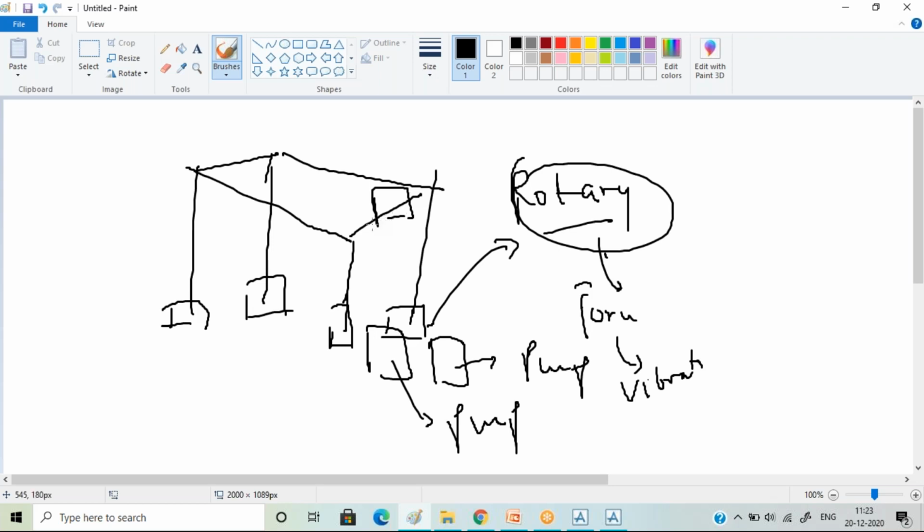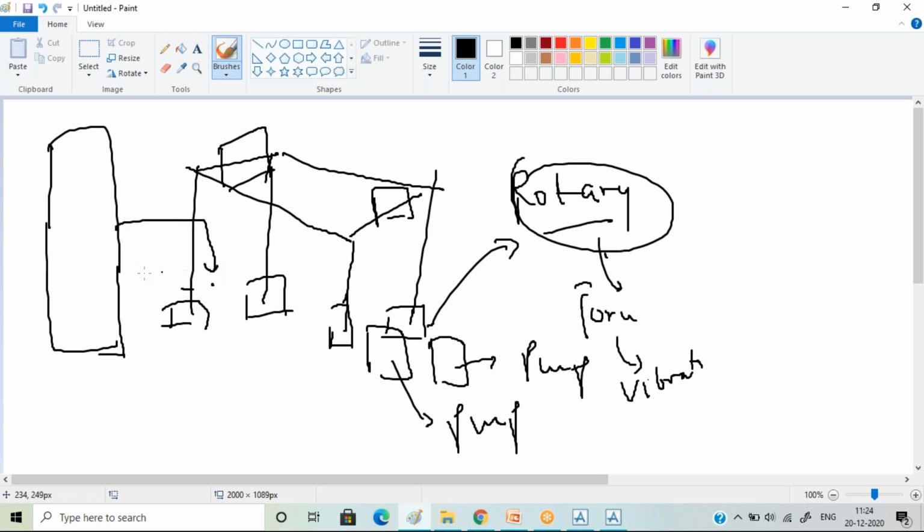And the same goes for your other equipments, like a reboiler. You must have seen that in the case of columns, reboilers and a condensate pot, there is a certain amount of distance to be maintained. Say this is a nozzle which is coming from a column getting into the condensate pot. This is a vapor line. There is some amount of distance to be maintained between this and the condensate pot.